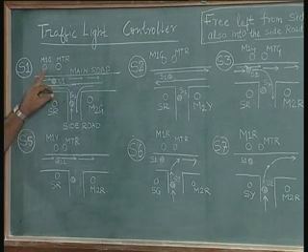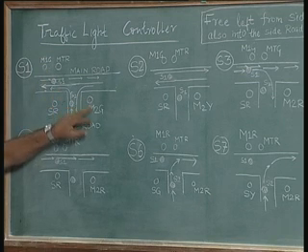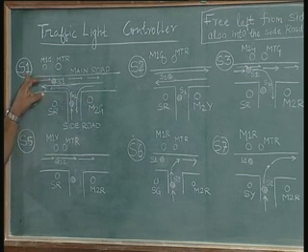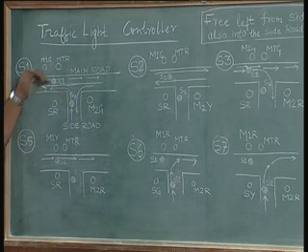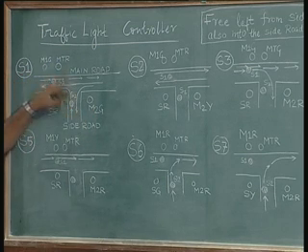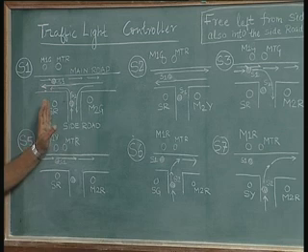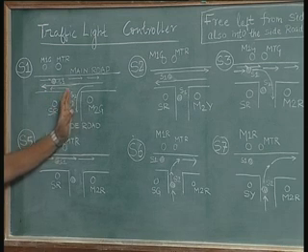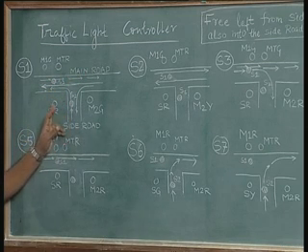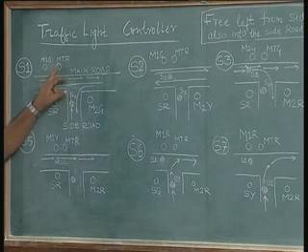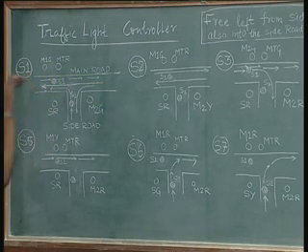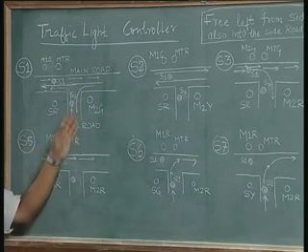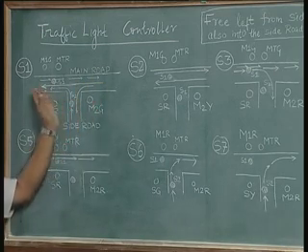That means the main road is green in both directions. The first diagram here: M1 G, M2 G. The side road, the traffic turning into it, MT, is red. Similarly, the side road here for turning from here into the main road is also red. So this side road is red, this turn signal is red, the main signal in both directions is green, and traffic will flow freely as well as turn into free left and free left.